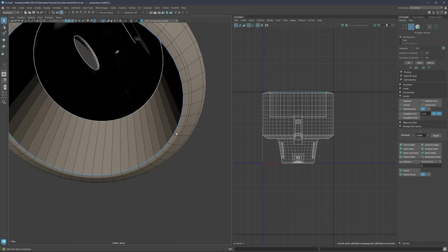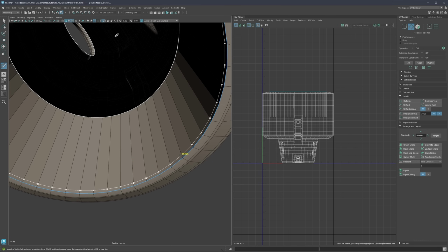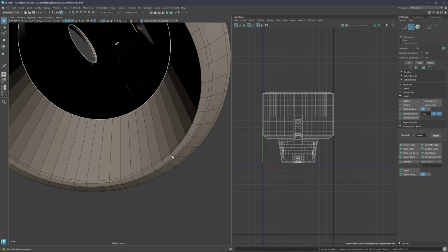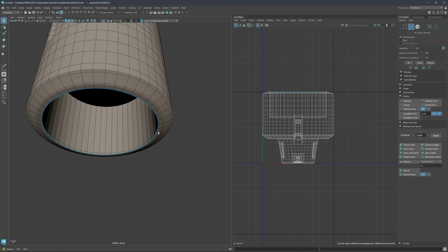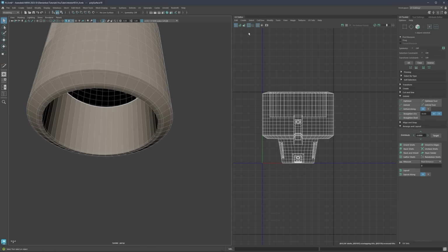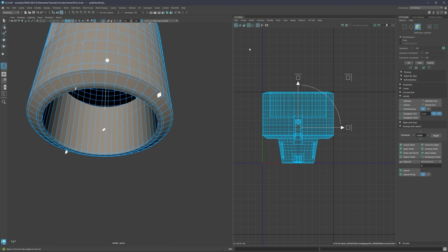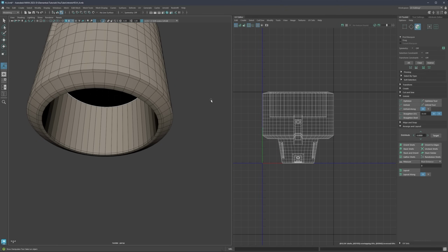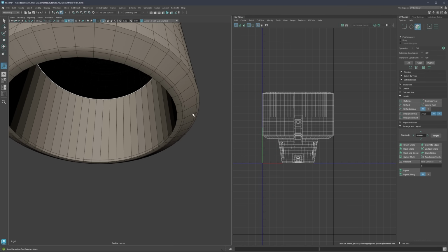But first, before we do that, I would like to create a cut right here so that we have the least stretching and that we have the proper seam. So let me just go here one more time. Let's select everything and then create planar. So you don't have to delete it. You can just create a brand new one. You're going to see that each time you get new UVs, so it really doesn't matter. You don't have to actually delete it.